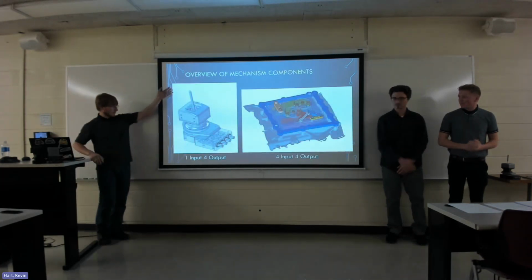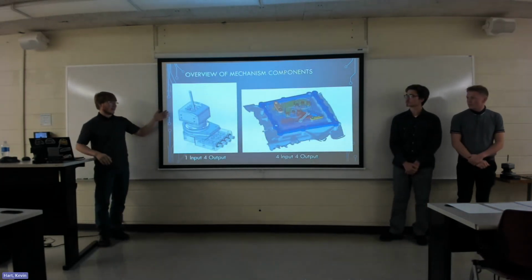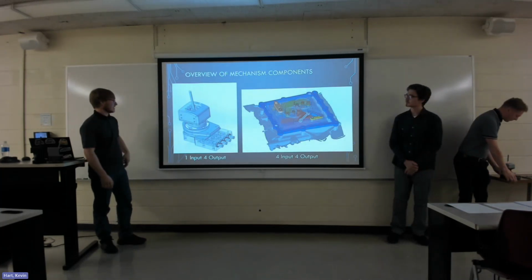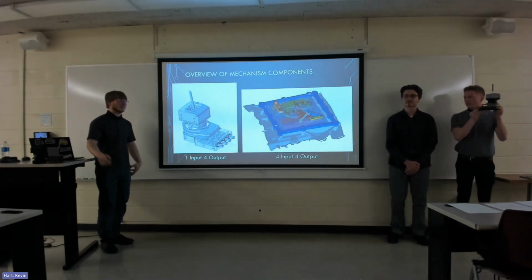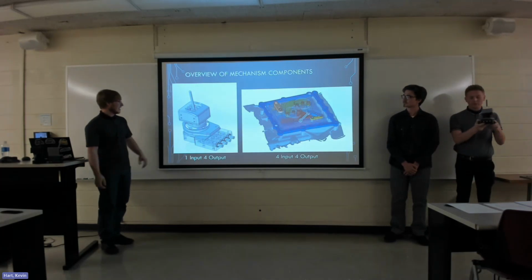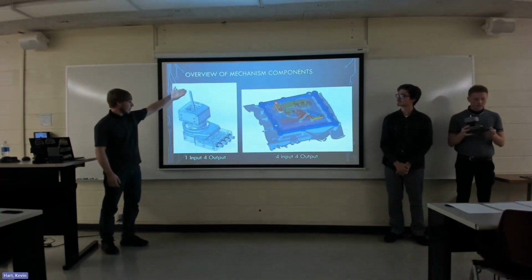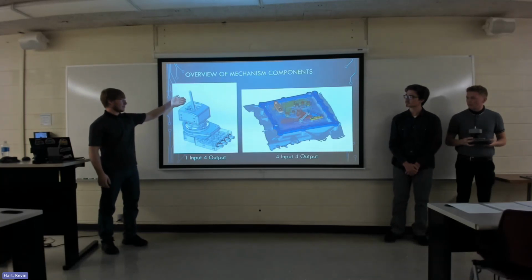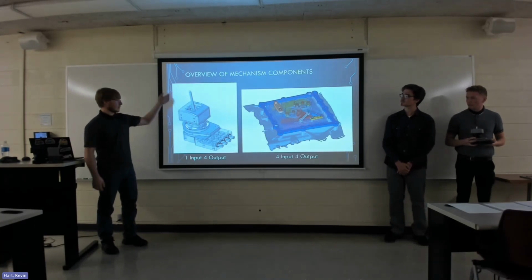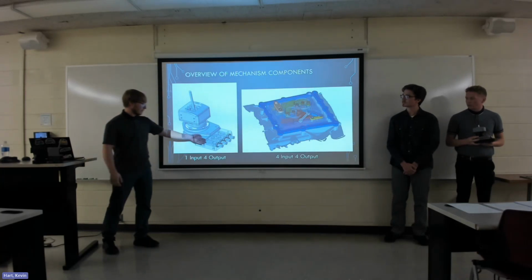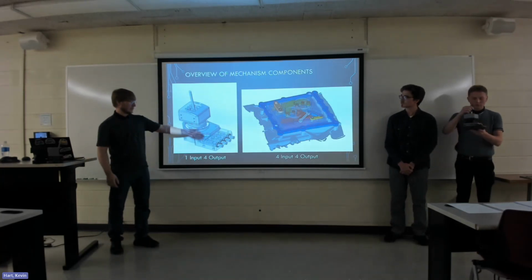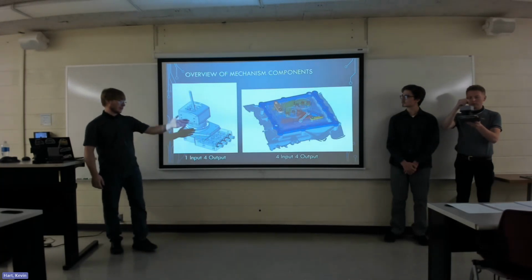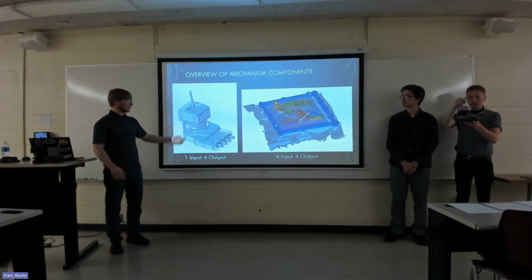Here is the gated four rod output shifter that we were just talking about. As you can see, the driver interface is gated, as you might have seen in some exotic cars. Basically we have one input from the driver. We have a number of gates. Each of these has 3 positions, so you can be in neutral, engage forward, or engage backwards. Then we have the 4 output rods. Each of these output rods can either be in neutral, which is centrally located, engaged outwards, or pulled inwards.